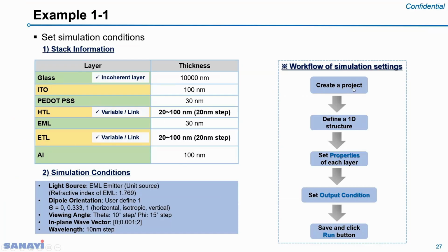At first, create a project and define a structure in the stack list. After that, set properties of each layer and then set the output condition. Lastly, save the project file and click the Run button.